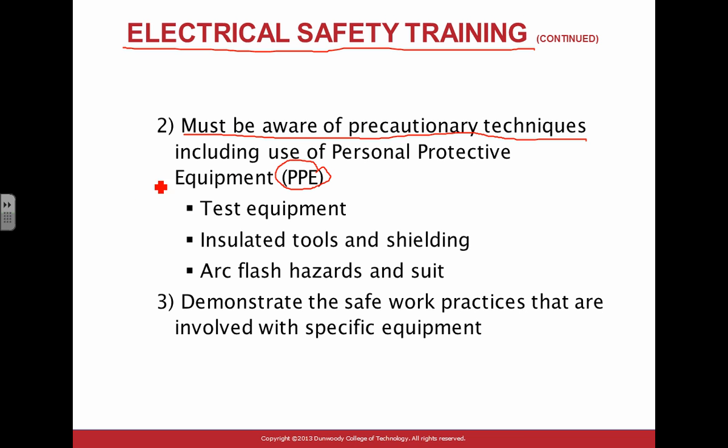So, selecting your PPE, and the document that we give you guys is very simple. It gives you a few things to do. We select the PPE and also the test equipment, and insulated tools are part of your PPE. Can you use this meter on the 480, 277, 4000 amp switchgear? I hope not, because I'm not kidding you, not all meters are created equal. Be very, very aware.